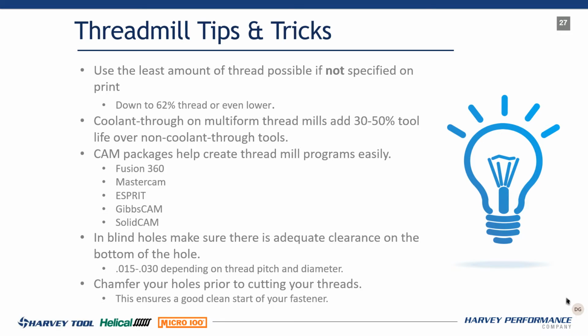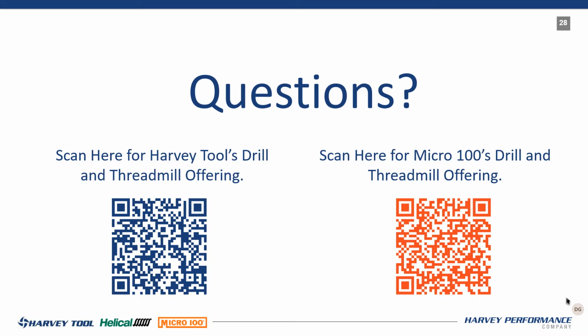Blame the drill, okay? Nine out of 10 times if your thread mills and your taps are breaking, it's the drill's fault. You're work hardening the hole. So take a look at your drill application. You can fix that work hardened hole by adjusting speeds and feeds or getting the right geometry on a drill, and therefore your thread mill, your taps will have a better time to sustain and live.